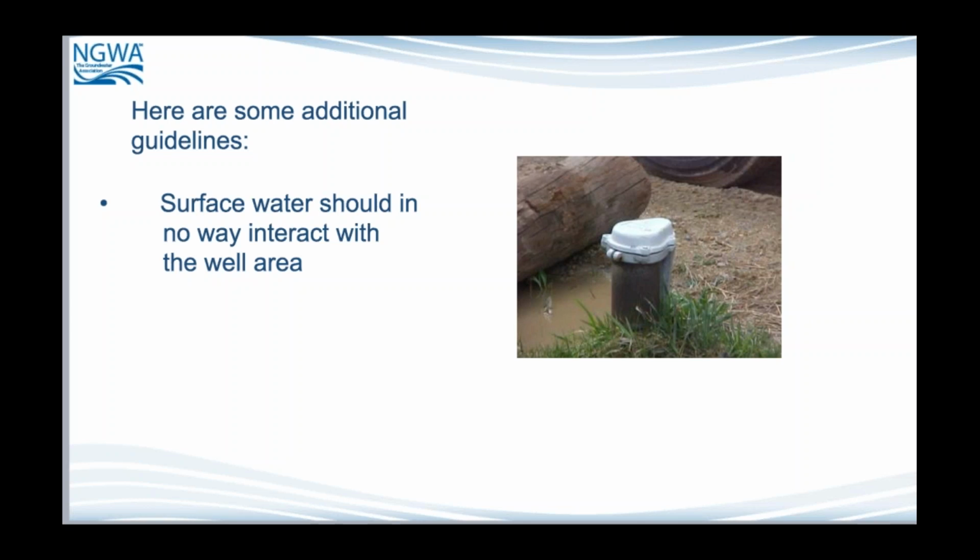You never quite know. So if you let it slope towards the well, and you have a much, much older well, there's no way to know 100% which one you've got based upon the age and things like that, as to how far back you go. But if you have an older well, there's a possibility that that water could be seeping itself down to the aquifer. You want to make sure that you slope that away from there so that that contamination does not have a chance to find a way down by that casing and down to where it's going to be inside your well itself.